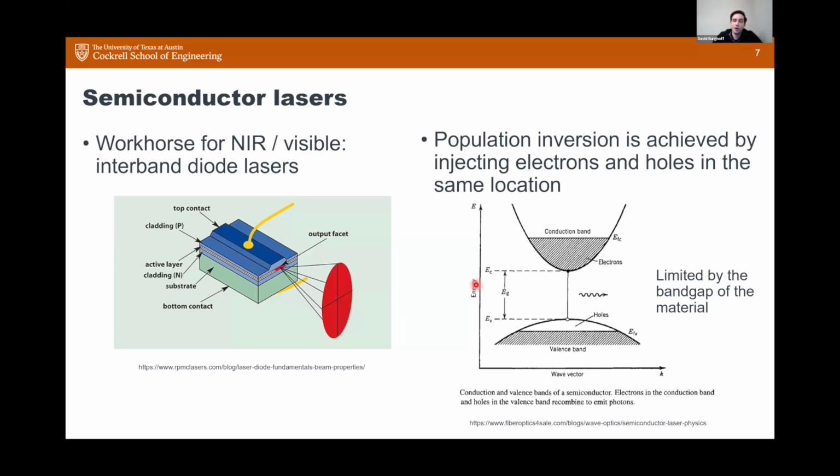So if you wanted to make something that's lasing in the terahertz or even in the mid-infrared, that's very challenging just using a conventional semiconductor material. Now there are actually low band gap materials, like for example mercury cadmium telluride, but actually there's a secondary issue when it comes to low band gap materials, which is that it's very difficult to achieve selective injection. So in low band gap materials, in other words, it's very hard to actually achieve any population inversion at all.